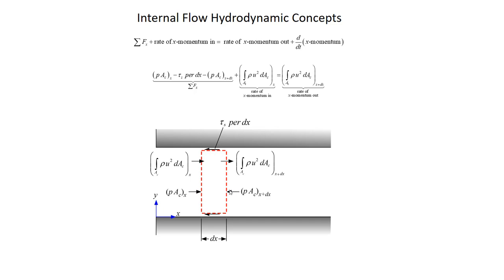Why do I have to push the fluid forward? Because there's this force up here on the wall trying to hold the fluid back, and I have to overcome that. And the other reason I might need a pressure force is if for some reason I have more momentum leaving than I do entering, right? Those are the reasons why I'm going to need a pressure gradient that's negative. That's why I'm going to need a higher pressure on this side than this side. That's physically what's going on.